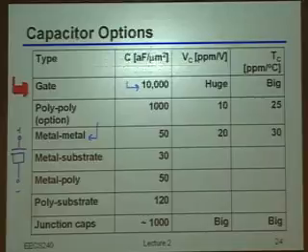Now, by the way, thinking a little outside the box, let's say you really needed really, really big capacitors. Is it a good idea to take a sea of transistors and cover your whole chip in gate poly like that, or might there be a problem? Okay, there's indeed this leakage thing that we talked about. That's very true. The specific issue I'm thinking of is directly related to that leakage. You can short the positive.